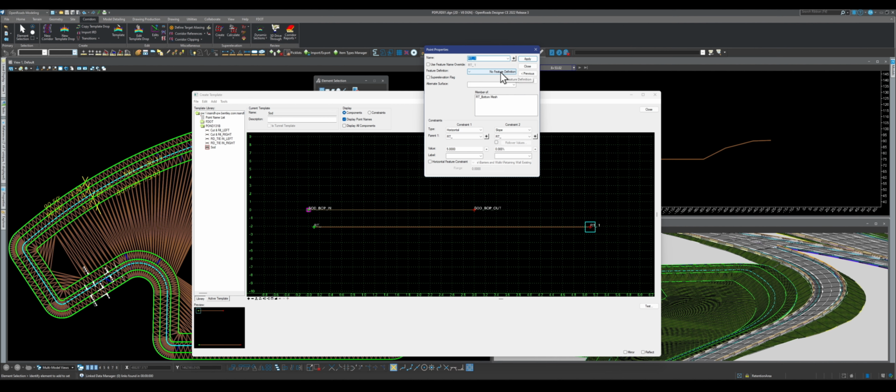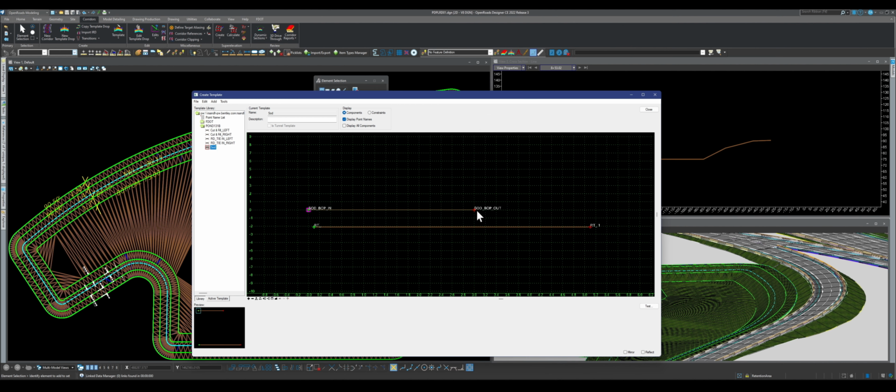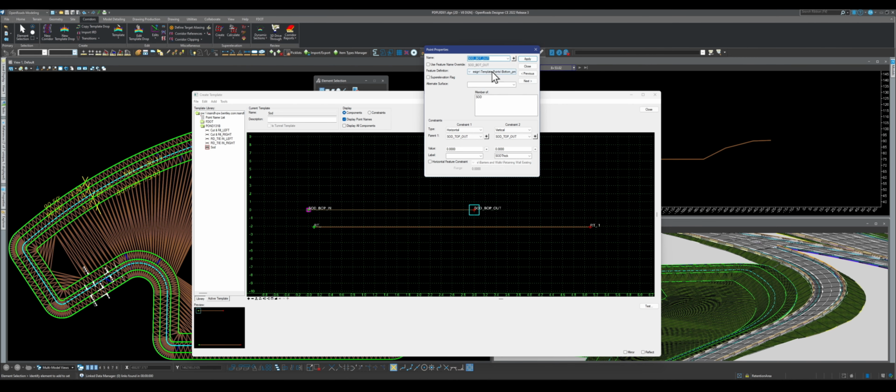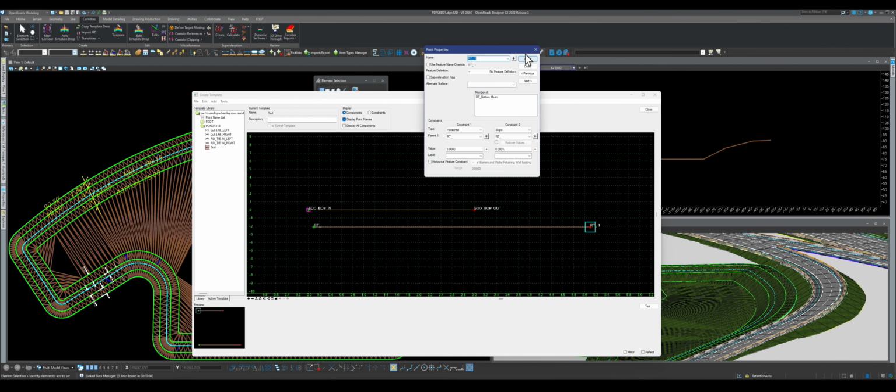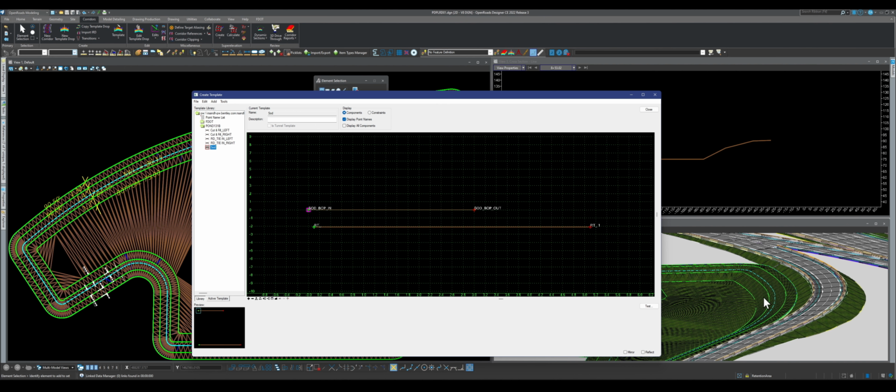And also, I forgot the feature. The points themselves also have features. So let's open one of these. As you can see here, it's basically a template point. You come here to the point and then you do linear and the roadway design and then template point, and then whatever it is, since it is a sod or a slope, you can call it slope break or pick the slope break. It doesn't matter. These are not that important, especially for what we're doing here.